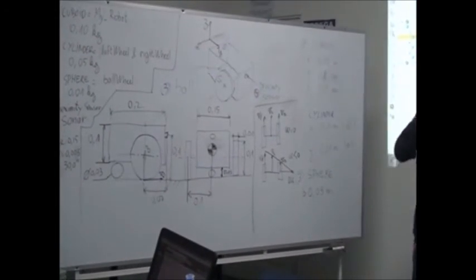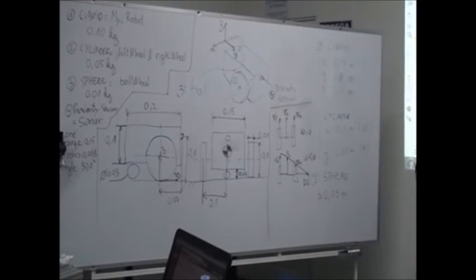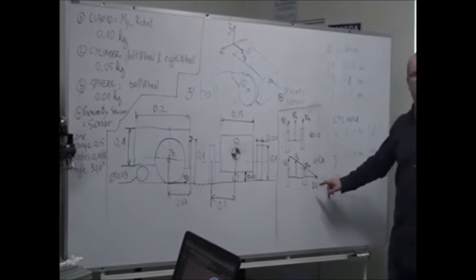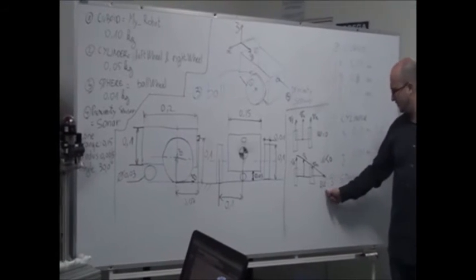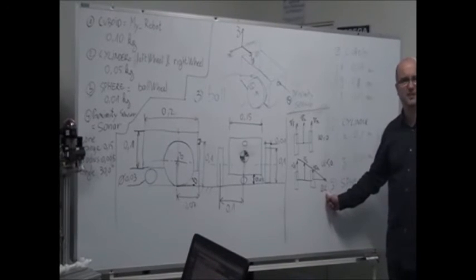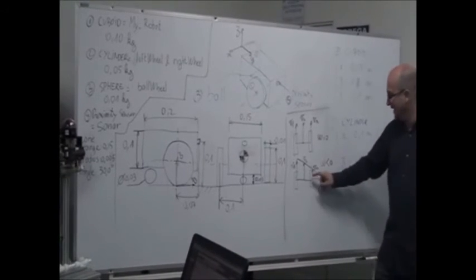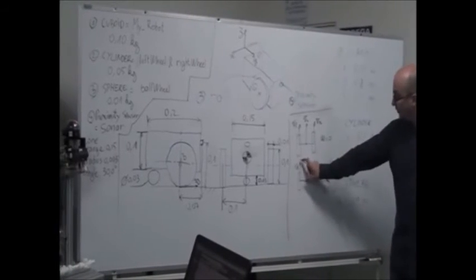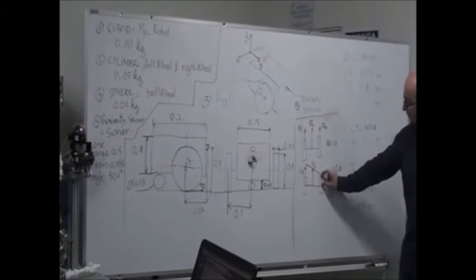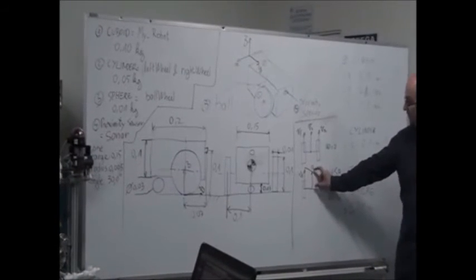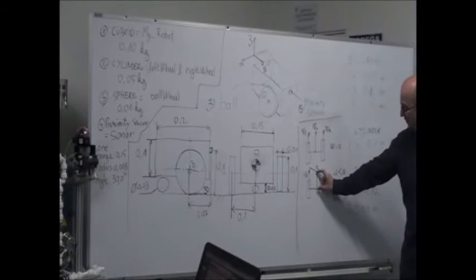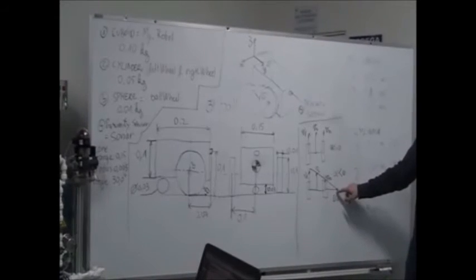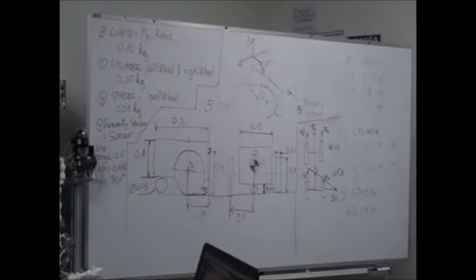And what will be the point of rotation? It will be here, the instantaneous center of rotation, ICR. Anyway, it will be like that. To detect it, it's easy with the model. You put your vector of velocity of 10, vector of velocity of 5. You will have a vector of velocity of 7.5, half the way of that, and you will have an angular velocity also. And you will be rotating around this center here. Let's do that, just to see if it works.